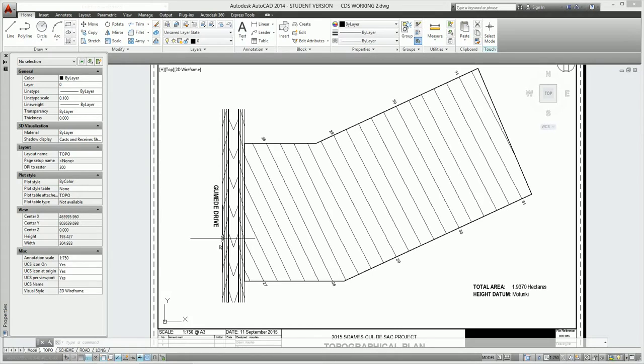Perhaps interesting to note the typical set out here for the road contours. As we can see here, as the contour is coming across the berm, which obviously is at 4%, then it flattens out a bit for the footpath, which is at 1.5%, another 4% berm, and then it goes quite sharply across the curb and channel, which of course has a 100mm drop, and then back into the road with the fall of the road and the high point in the centre line, and back out and mirrors out the other side.